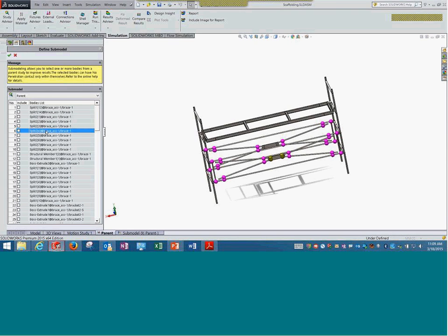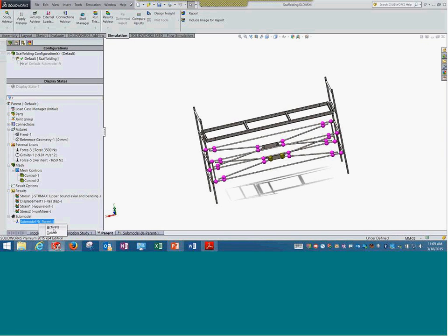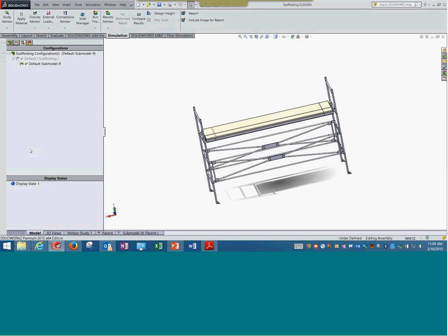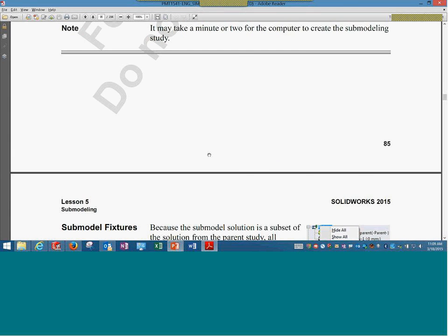yes, it is helping me create. So this particular dialog box is where I can select the parts that I want to use for a submodel. So instead of creating a new one, I'll use the existing one, activate it. And so in the study, we have selected those 3 localized parts, which you saw a few minutes back. On these 3 parts, you can change the quality of mesh, other details, and do the analysis. That's it. Else I can explain in this topic.